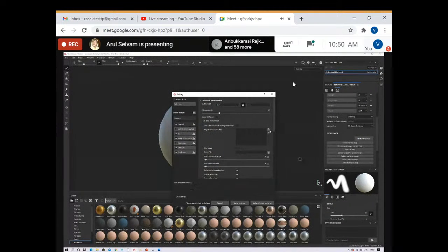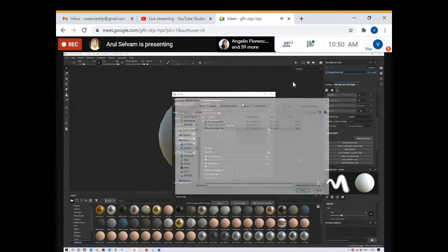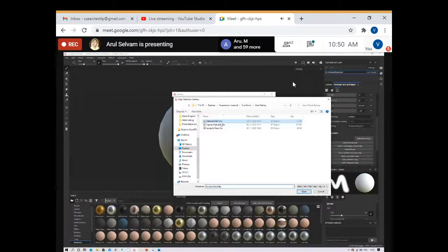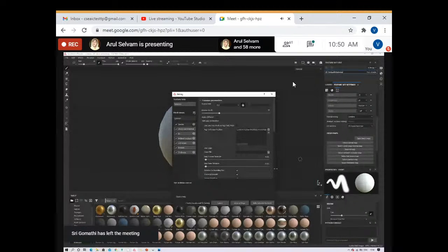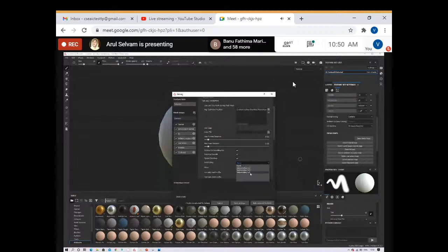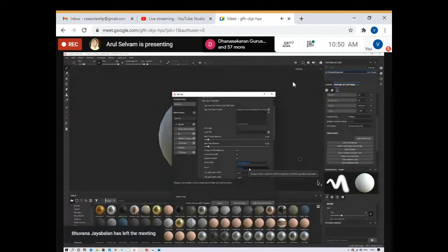In this dialog, I'm using the high definition mesh. Select this mesh and say detailed mesh, which is 12,800 polygons. I choose this detailed mesh and say open. Then the projection, how I'm going to project to the surface. Maybe the intended low poly model is a smaller one or a bigger one. But anyway, it has to be from the surface, 0.05, some default value that I use. And also some anti-aliasing resolution where I give 8 by 8. Once this is all over, bake selected texture.